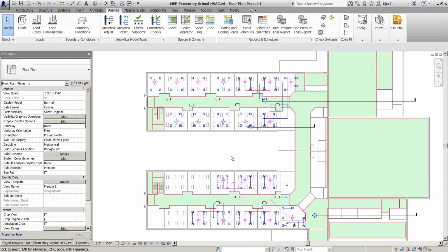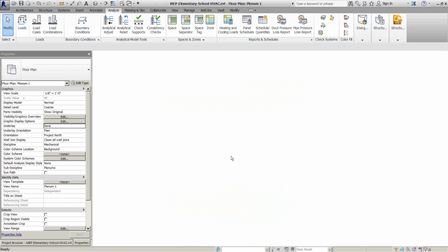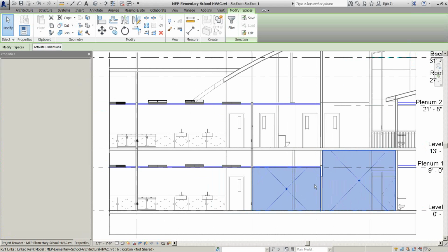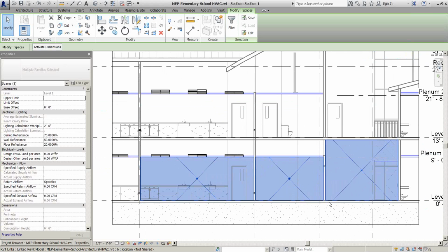Because you have no plenum spaces set in those, is why it's a different color. Right, but why am I seeing any blue-green seafoam? Because those are waiting for you to add plenum spaces to it. No, that's a good guess, though. Those are the ones that already have spaces. Because the space already extends up into the plenum, it goes up to the slab above, those areas basically don't have a drop ceiling. So they're not running into that bounding element. Right. Those are hallways in the big gymnasium. Yep, exactly. Kind of what I was getting to. Okay. So you're right.